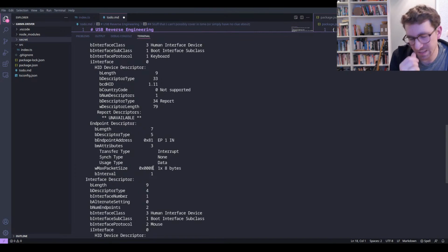transfer type and also endpoint type, right? They're kind of tied together, transfers and endpoints. The one final endpoint type is control, which is the control transfer. It's more initiated by the host, but the host is basically doing some aspect of control to the device itself.